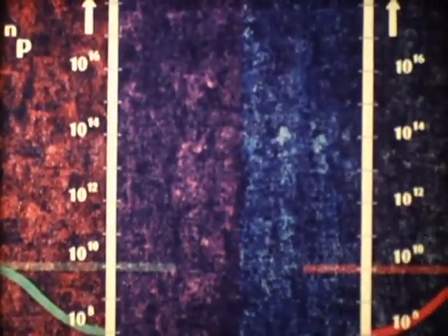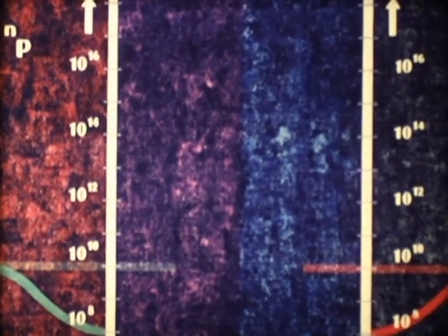When a reverse voltage is again applied, the barrier is enlarged and the minority concentrations decrease, for example, to 10 to the 8th per cubic centimeter. The numbers of charge carriers flowing across the barrier are proportional to these deviations, which are numerically equal to 10 to the 10th minus 10 to the 8th. The latter number is so small that it can be neglected. The same result is obtained when larger reverse voltages are applied.